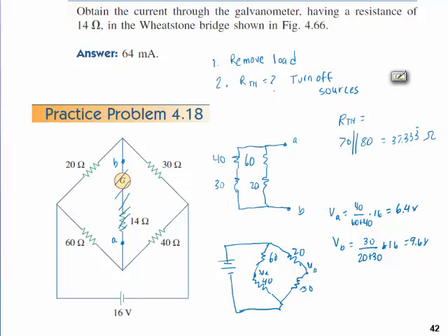Okay, so now it says what is the current in there, but at this point I have V Thevenin, because V Thevenin is this voltage. It's the voltage drop at the open terminals right here with the source put back in. So V Thevenin is VA minus VB.